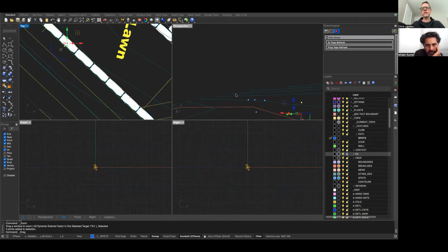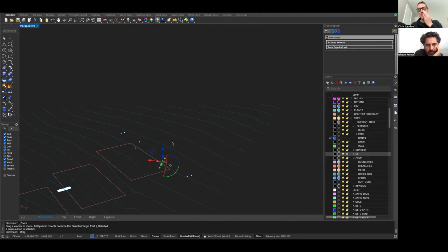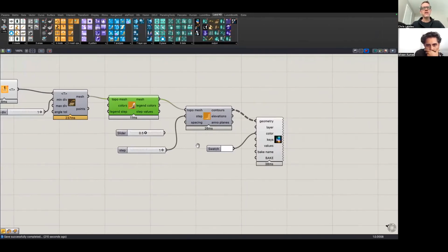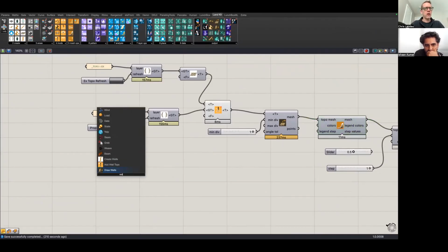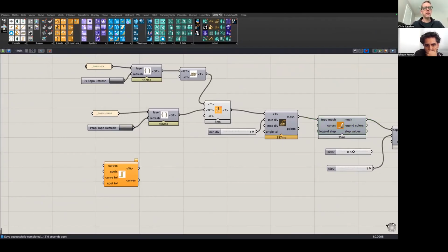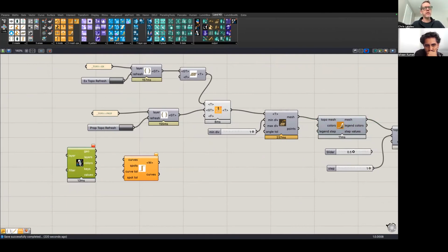And you can see what we're doing. We've got spots that let the wall taper into the grade, right? So how do we turn that into an actual wall? That's the tricky part. So then we're going to create a wall, create wall, and we want curves. So we're going to do a layer pipeline. And this is one of our new components.